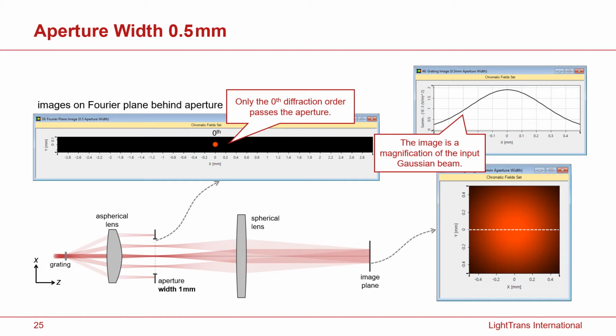learn from Abbe's theory. And in this system, you see that we can combine different kinds of technologies. We use solvers for lenses, solvers for apertures, and solvers for gratings. In this case, especially, we are using an RCWA rigorous solver for our gratings. And we have the coherence of the light under control. Finally, we are making a coherent summation of the different diffraction beams, and we make the image.